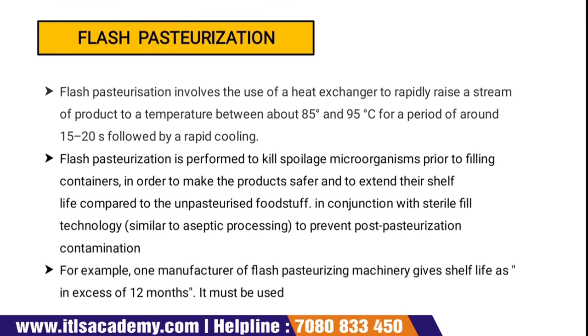Then flash pasteurization is performed to kill spoilage microbes prior to filling the container, in order to make the product safer and to extend its shelf life compared to unpasteurized foodstuff. It is used in conjunction with sterile fill technology, similar to aseptic processing, to prevent post-pasteurization contamination.